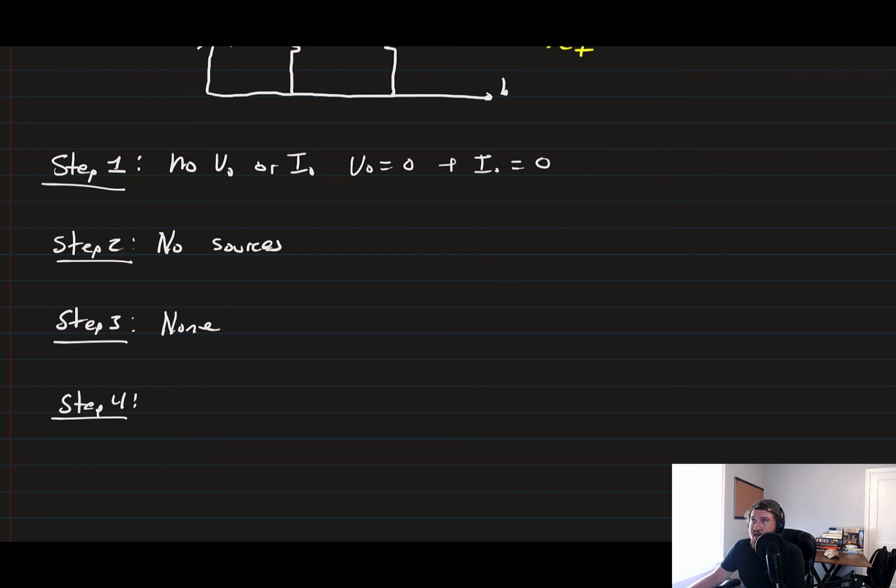Let's go ahead and jot down our equations that we had before. Remember our voltage and current relationships for our S-domain circuit elements. So we have VR is pretty easy. VR is just equal to R times I sub R for our resistors. Our voltage in an inductor, VL, is equal to S L I minus L I naught.